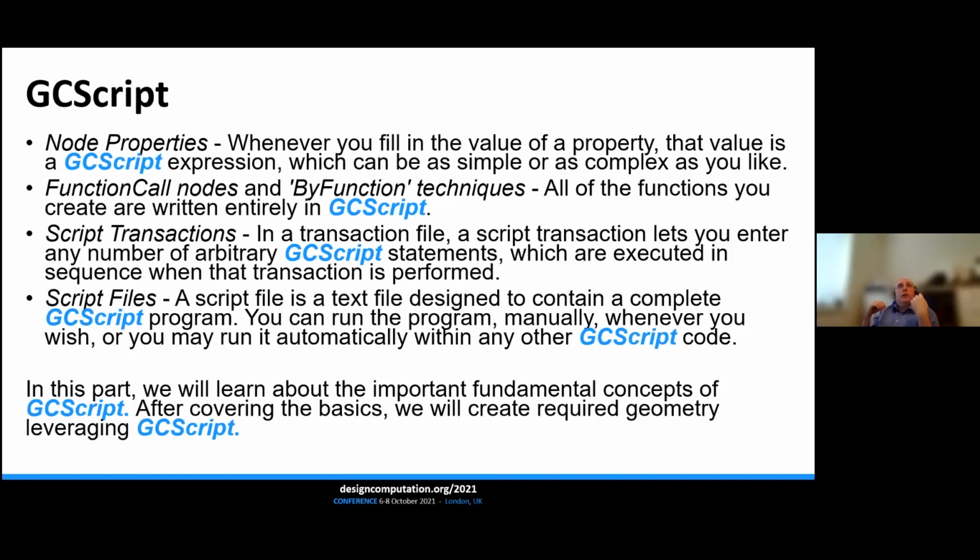And so long as you have the GC application, you can see the node tree, you can edit it, etc. Alternatively, you can export the entire graph as a text file that we refer to as a GCT file, a GC text file, and then import that into another session and have it rebuild the graph. So that's also a possibility, because it's an uncompiled text file essentially that we're using. Okay.